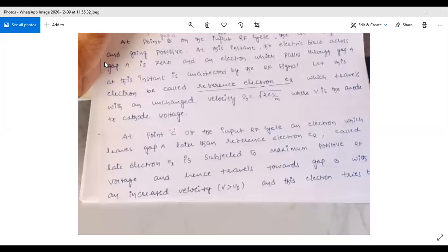Okay, see here. Once again, I'm repeating that point, no problem. So, two cavity Klystron amplifier, we know the meaning of amplification. Finally, what happened is that at this position there is actually no bunching. But here, because of this RF signal, suppose I apply a small RF power signal, the electrons are traveling with different velocities, and all are bunched together, maybe at this point or at this point. Here only a few electrons, so no bunching here, but here bunching is there.